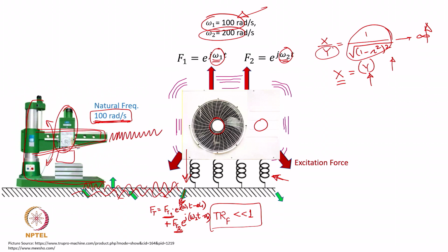Now, what is going to happen? You are going to operate this machine for some finishing operation on your delicate structure being manufactured, and if your tool itself starts vibrating, then that vibration is going to create products of bad quality. And this has happened in one of the factories nearby. There were a large number of rejections of the components being manufactured only because there was a heavy forging hammer operating nearby, and the isolation was very poor, and that can create trouble.